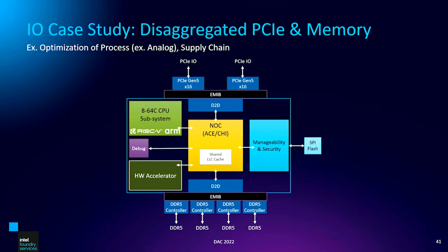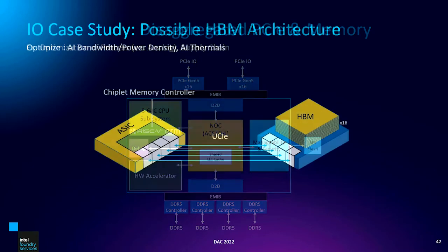You could also have different DDR technologies. In some cases, you want DDR4 technology because it's more mature. The yield is up, therefore the cost may be less. And in some cases, you want DDR5 technologies. It has greater RAS capabilities, as an example. And people want different speeds. By the way, DDR4 and 5 are architecturally incompatible. They're very different. So the only real way, or a convenient way, to do a 2-for-1 design would be to create a chiplet technology that enables this, okay?